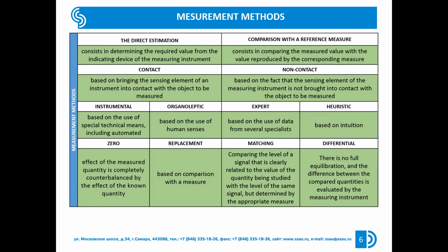For example, measuring the radial run-out of a cylindrical part, which is influenced by the eccentricity, ovality, etc. Checking the position of the profile on the limit contours, etc., as well as evaluating the surface roughness on the sample visually or by touch.